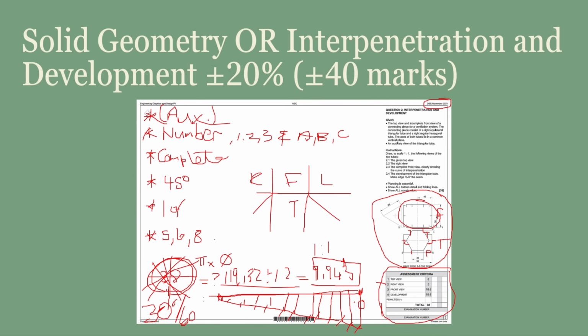So make sure that you are able to draw a pentagon, hexagon, octagon, any orientation as an auxiliary view, because you are most likely going to do this. When there's center lines needed, you add center lines in. Just like with the numbering of a geometrical shape, you will also need to number the circle 1 to 12, where it's applicable if you needed to do a cylinder.